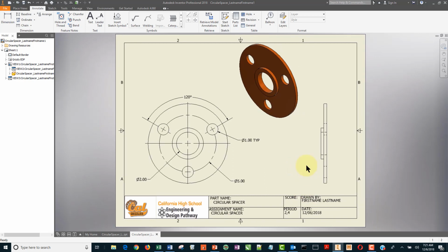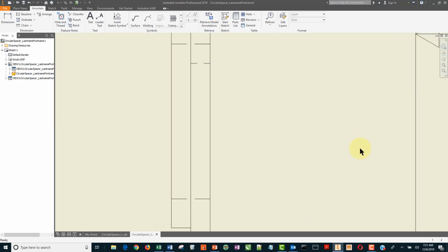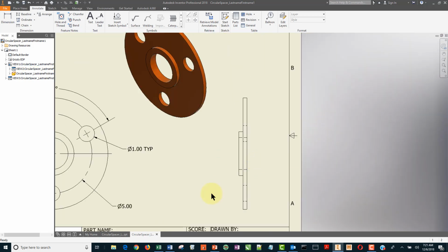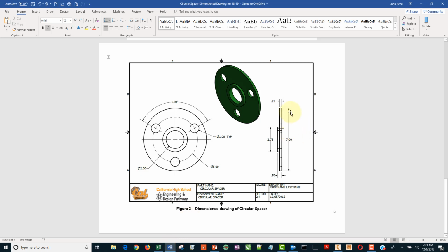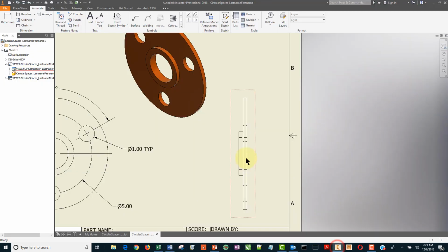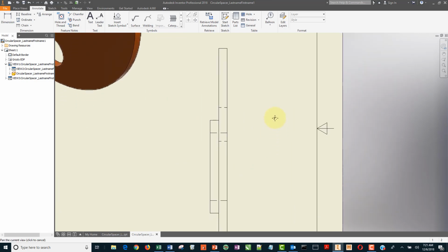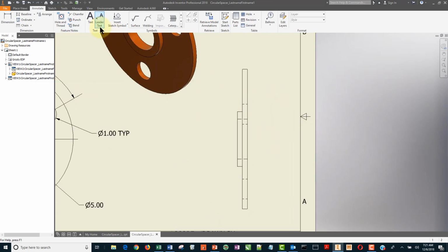Alright, so now we can come over to the right view, and that one is unfortunately pretty thin, but it's not that big a deal. We can use the scroll wheel to get as big as we want. And let's go ahead and dimension the diameter of it on the right here. So I'm going to zoom up and come here and grab there to there and pull out.